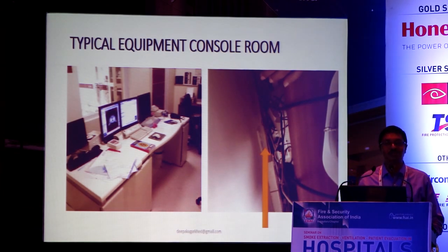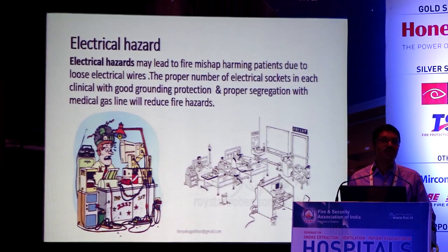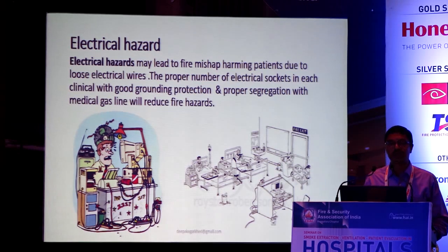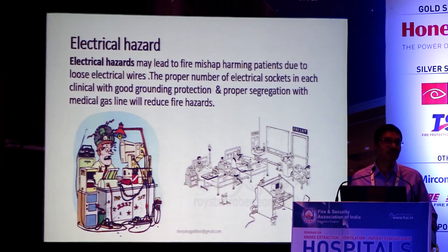The major issue which comes because of medical equipment is electrical hazard. Because of the one incident which I talked about initially, we draw more power than what is required. The cable capacity is not there, and it is an oxygen-enriched environment. All these things will ultimately lead to a fire or a mishap. So electrical hazard is something we need to look into when we are talking about medical devices.